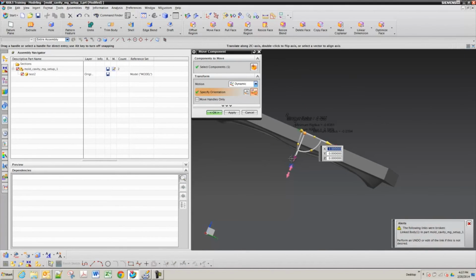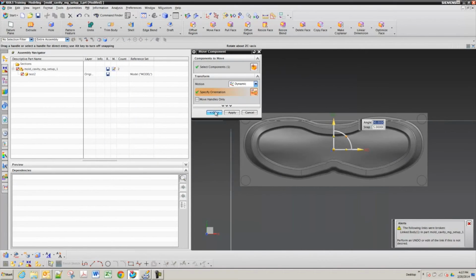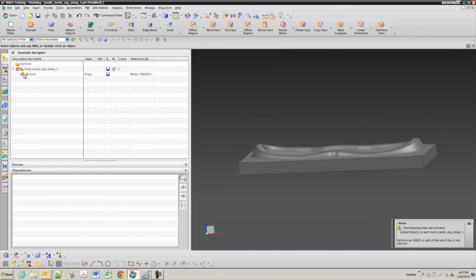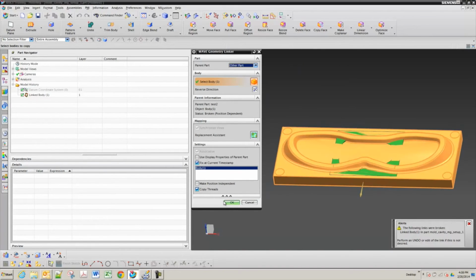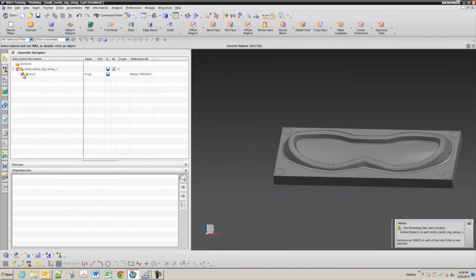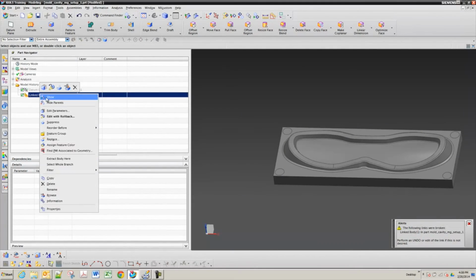Yeah, I just wanted to make sure. So flip it. And then rotate it. Okay. And I mean, if you didn't relocate it, it's still going to find where it was at. It would still work. It's just, might as well put it in the right orientation. So now, whoops, not hide it yet. Now I'm going to double click my link body and pick this new part and say OK. So there, now my link body reflects this new part. It's hidden, but it reflects it.